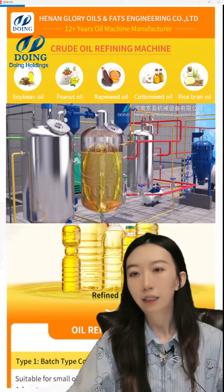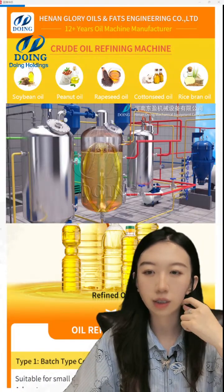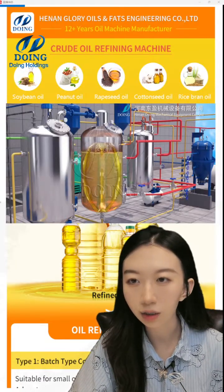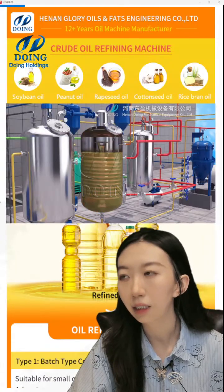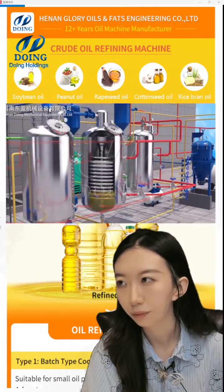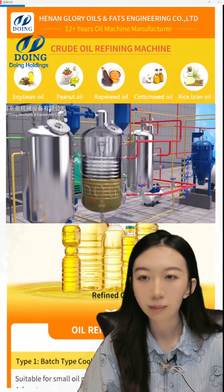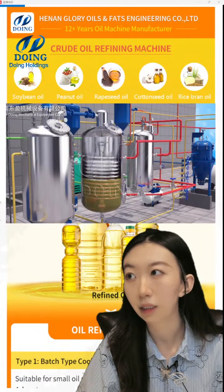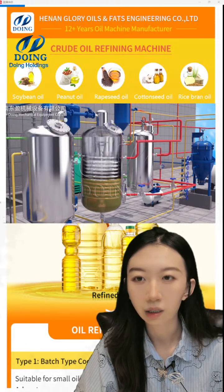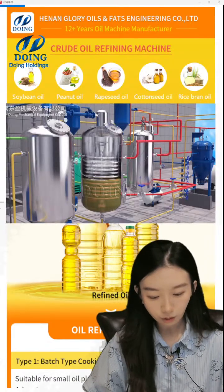Okay. In the past, I introduced the refining process, which includes degumming, deacidification, decolorization. Next, the last step is deodorization. In this step, we should first vacuumize the deodorization tank to prevent the oil from oxidizing.